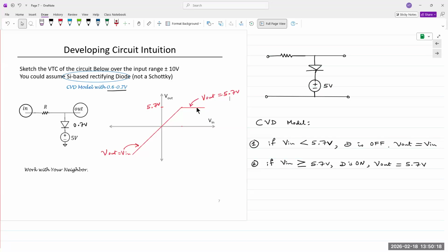Yes, is 0.7. That's just provided to us. Oh, question being asked, why does it combine? Is because the diode is connected this way. So the anode is here. Positive reference is at the anode, plus and minus. So when the diode turns on, it'll be a voltage drop. Actually, let me do it here. When it's off, it's an open circuit. That's clear to everyone, correct?